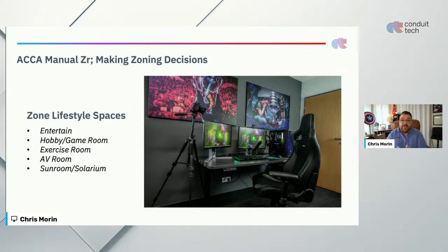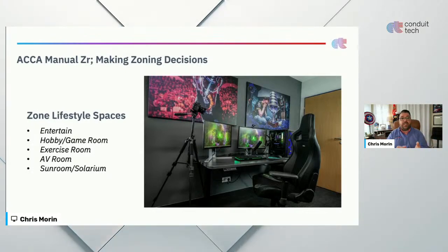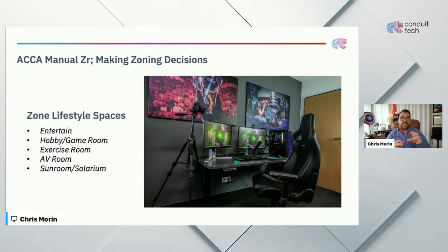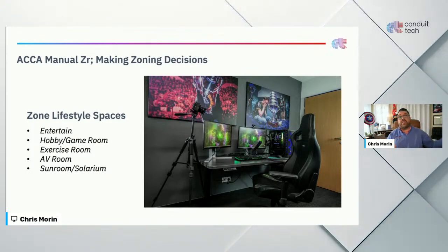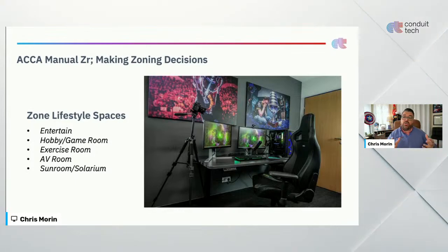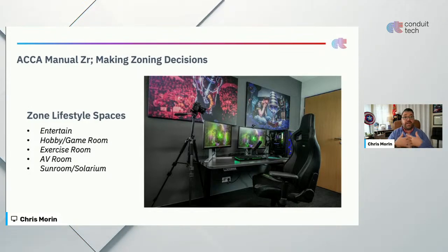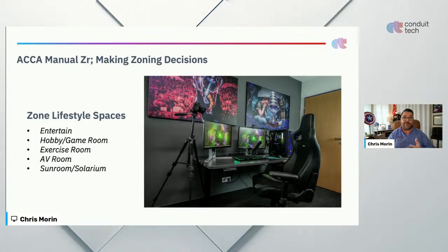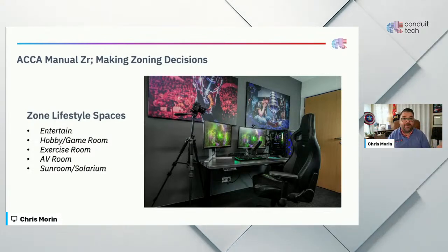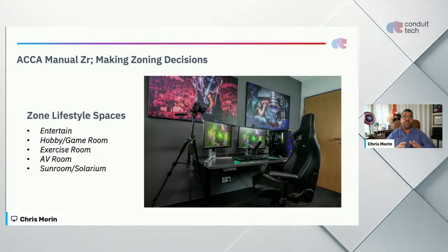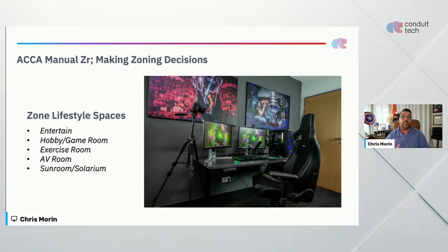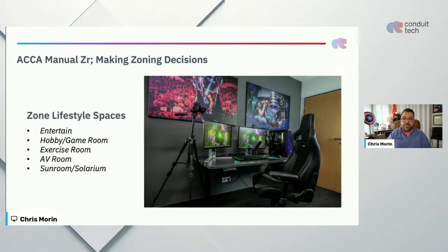So maybe you have entertainment rooms or a hobby or a game room, right? The needs in this space is significantly different than the rest of the home for comfort. So you're going to have to zone for lifestyle in that instance, right? And it's possible that what you consider a bedroom in a home for listing purposes on realtor.com or whatever, right, may not be what the homeowner is using it for, and they may never be comfortable if we don't zone that off, okay? And that could be, like I talked about before, in-law suite or something.